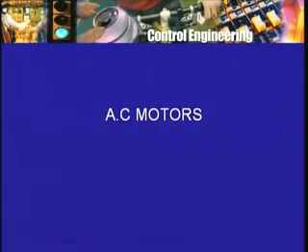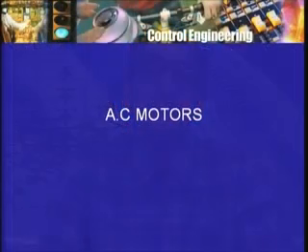Of course, today one may find that instead of DC motors, one may prefer to use AC motors, and one of the reasons is that what is available to you as power supply is not DC but AC. So AC requires rectification to DC and then use of the DC motor. This is still going on in the suburban railway system of Mumbai.